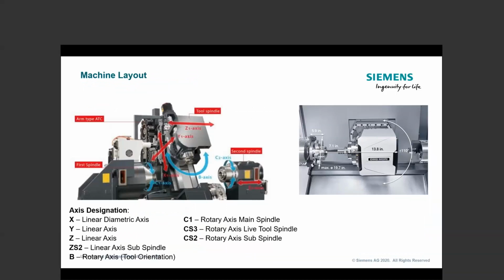Now here is a typical layout of a B-axis lathe. And we certainly see on the right side where you're going to now have a milling spindle that can be spun around. What's important to get your head around at this stage is where is B0? And it's a little different than we're used to thinking. Typically, when we think about angular offsets, 0 degrees is generally always 3 o'clock, right? And then if I want to go to 90, it's 12 o'clock. 180 would be at 9 o'clock, and around we go.